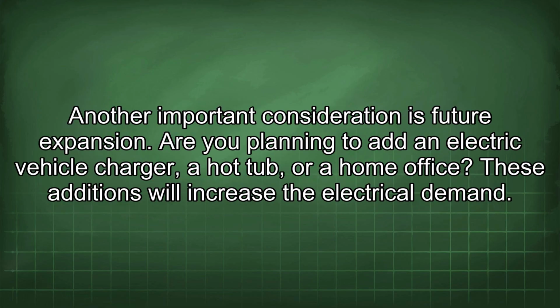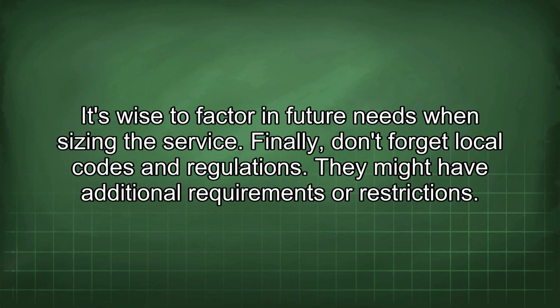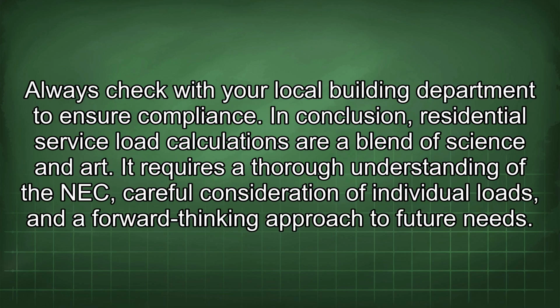Another important consideration is future expansion. Are you planning to add an electric vehicle charger, a hot tub, or a home office? These additions will increase the electrical demand. It's wise to factor in future needs when sizing the service. Finally, don't forget local codes and regulations. They might have additional requirements or restrictions. Always check with your local building department to ensure compliance.